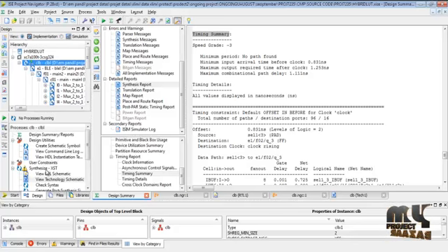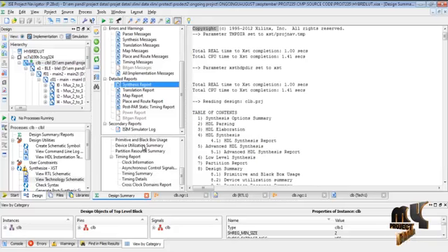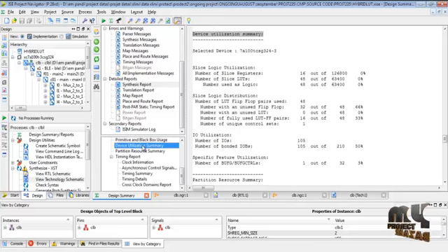In the implementation design, various reports are generated to simulate the synthesis XST and implementation design. In the synthesis report, we are able to view the device utilization summary and timing report. In the device utilization summary, we see how much of the devices we used in the proposed design. That means LUTs we used 48 and flip-flops 48, and bonded input output BRAM range is 105. These are the devices used in the proposed design.